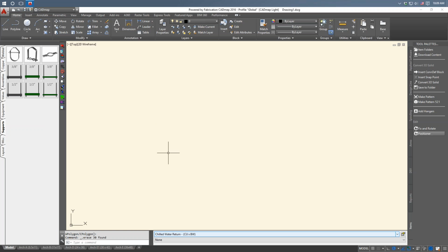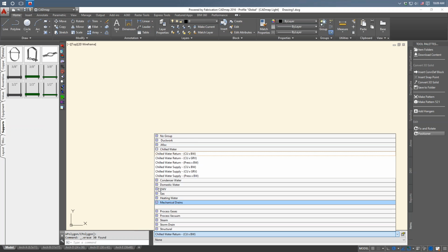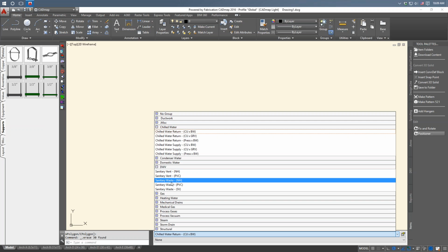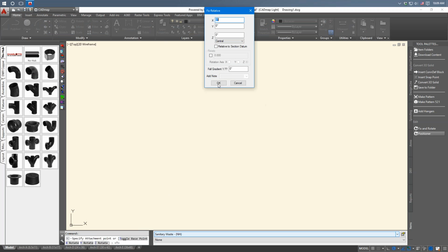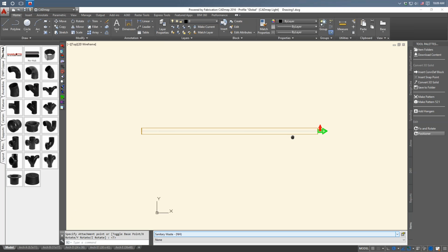And then another one just came in asking, so you said you could put slope on the pipe before you draw it. How would you go about that? All right, when I'm drawing with, say, no-hub pipe here, and I put my 4-inch in, I set my grade right here, 48. Height.